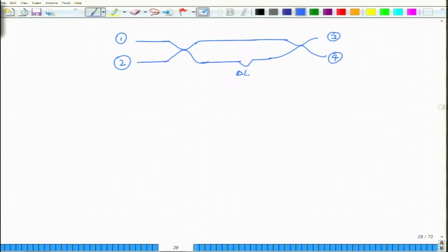So, when delta L is equal to 0 and you launch light only into port 1, it will split the output into two ports, and there will also be a pi by 2 phase shift here, okay, and assume that these two are 50-50 couplers. So, that makes our life a little bit easier to work with. So, when I send in light only at port 1, then this port 1 signal will be split into two, there will be a pi by 2 difference. Okay. When delta L is equal to 0, or you have delta L not equal to 0. So, delta L equal to 0 is the first case that we will consider. This will propagate with the same phase relationship. I am writing this pi by 2 just to indicate that these two components are pi by 2 phase shift away from each other.